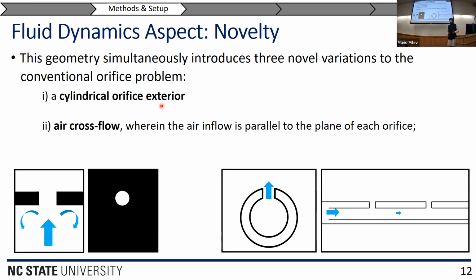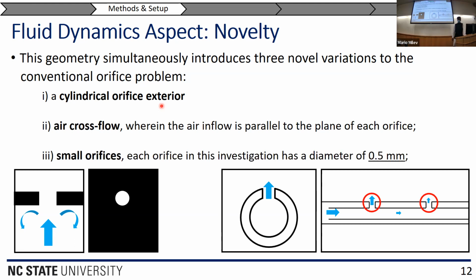And then you'd see a multitude of bubbles going through, and that's used for example in bubble column reactors and things like that. But also the orifices are typically not that small. 0.5 millimeter is smaller than, or of the order of, the tip of your pen. It's a really small size to resolve, in addition to the large sizes of the bubbles.